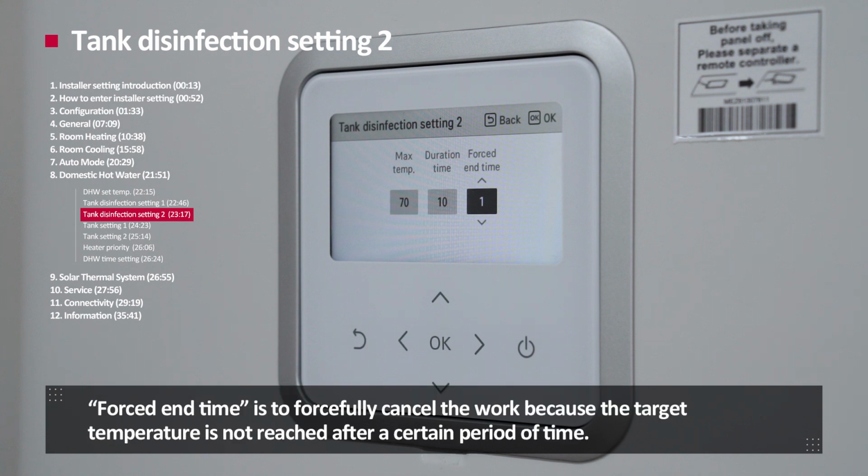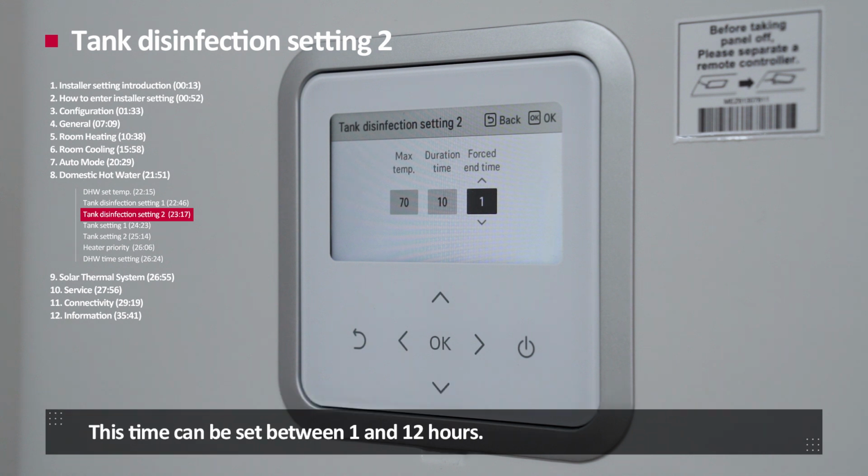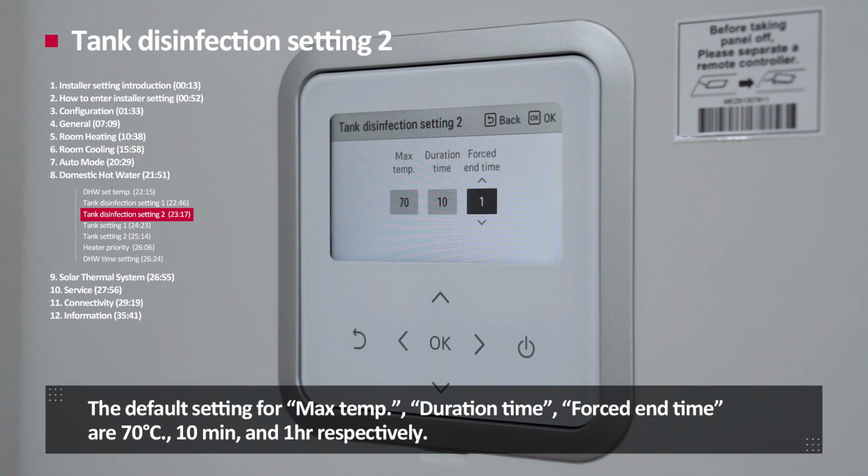Forced end time is to forcefully cancel the work because the target temperature is not reached after a certain period of time. This time can be set between 1 and 12 hours. The default setting for maximum temperature, duration time, forced end time are 70 degrees Celsius, 10 minutes, and 1 hour respectively.